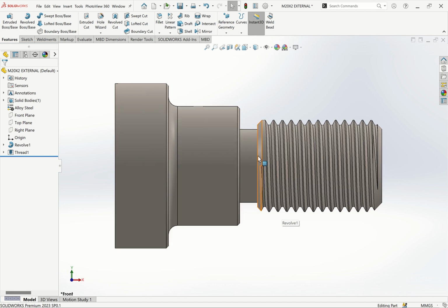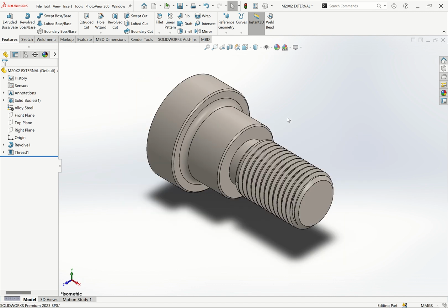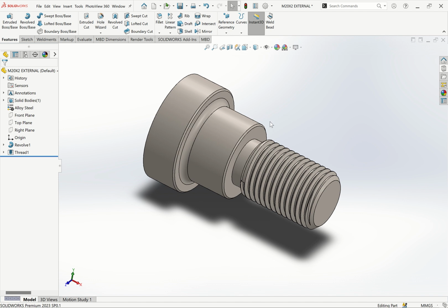This is a recess, or we call it undercut, so that it ensures when you're locking, it doesn't exit this section, and also for the purpose of safety. When you're doing a thread, it will not be a point of weakness. Okay, so that is what we have done for external thread.